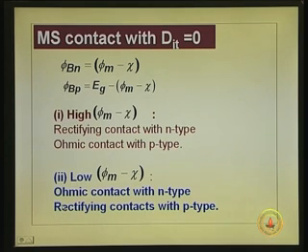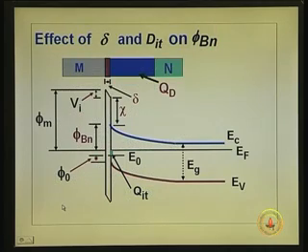Looks very simple, but things get complicated because of what we discussed last time, that is a thin layer of material, maybe dielectric material, and high density of states here in the interface does not give barrier height equal to phi m minus chi, but there is an additional drop coming up here.